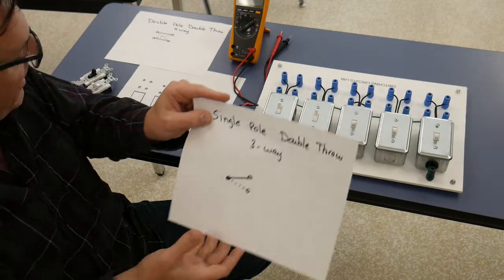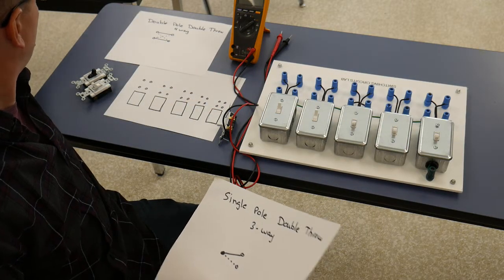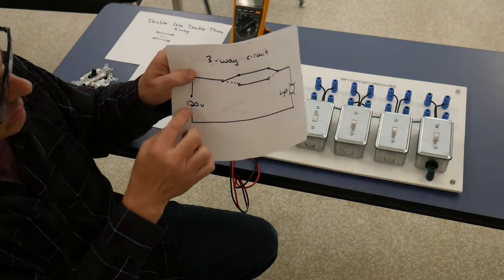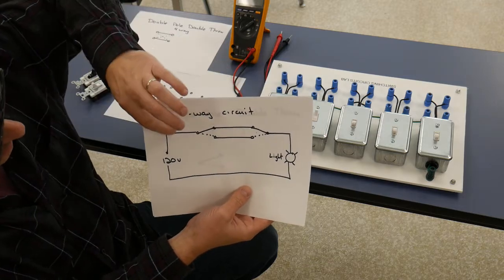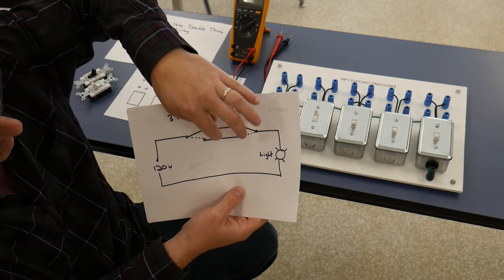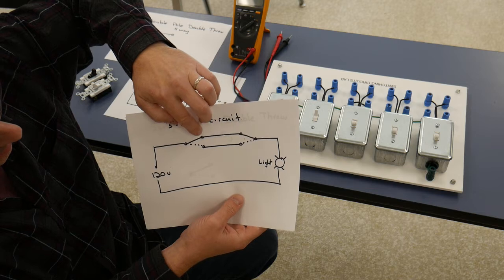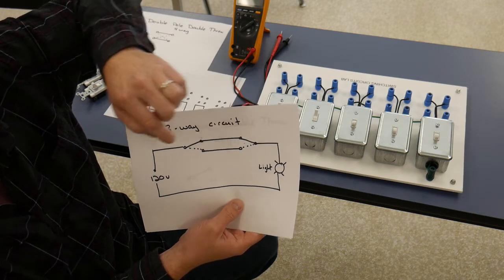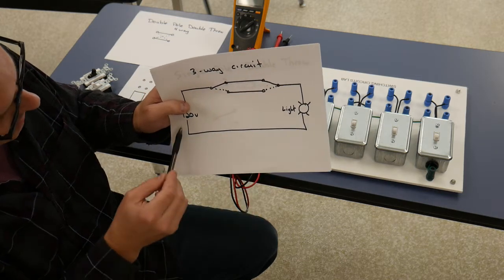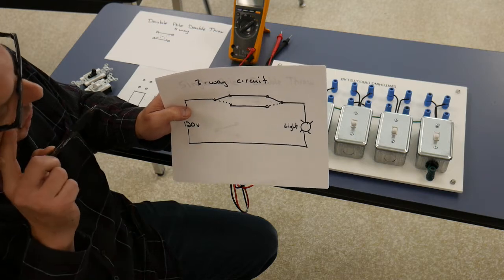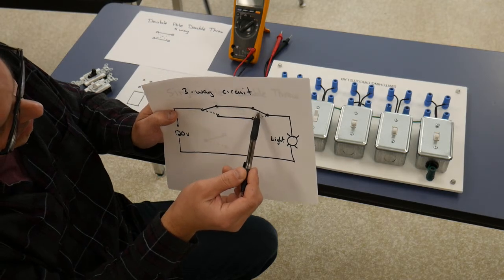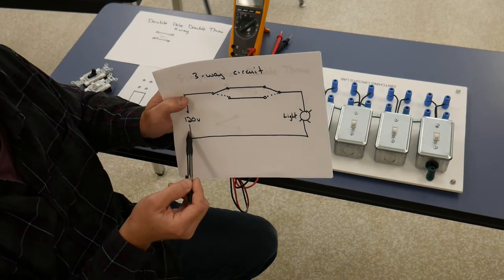The purpose of that would be to connect it up into a circuit like this, a 3-way circuit, where we have our source. We have our first 3-way device connected up to our hot, and then we have 2 travelers. These travelers connect up to the other 3-way switch over here, and then out of that 3-way switch we would feed out to the light and then back to our source. With the way that I have it drawn, current could leave this source here, head up through that paddle, along this way back down there to the light, and then return back to home.